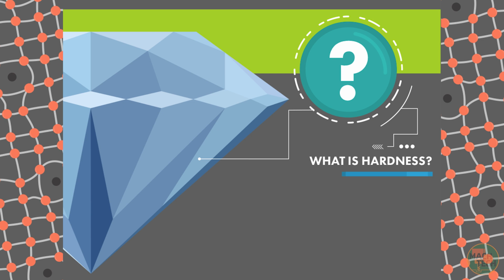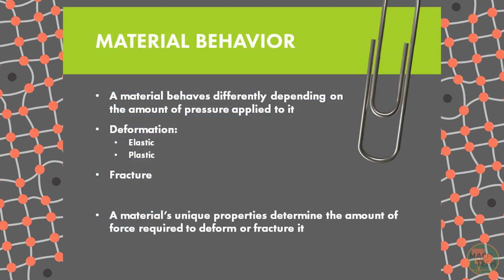Although this usually also goes hand in hand with increased brittleness. Once the material starts to deform, it usually fractures shortly thereafter. This is exacerbated in diamond because of the way it cleaves. You can shatter a diamond by hitting it with a hammer. In any case, we're here to talk about steel, which, like all metals, is a ductile rather than a brittle material. Ductile materials deform in three modes when an increasing pressure is applied to them: elastic, plastic, and fracture.